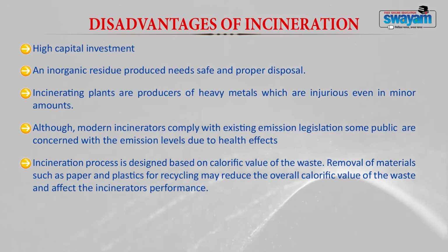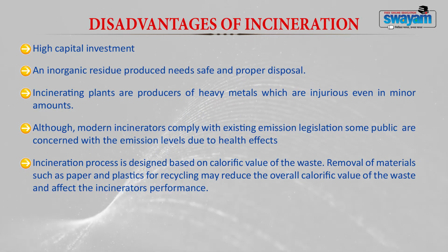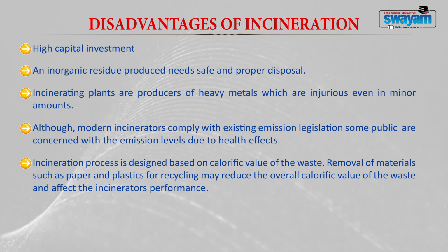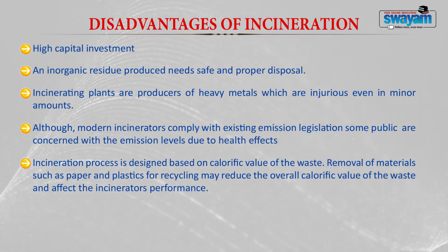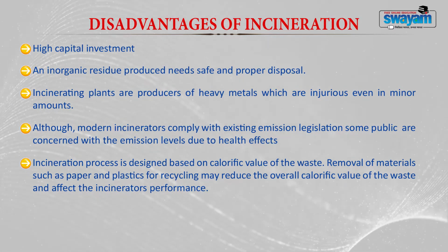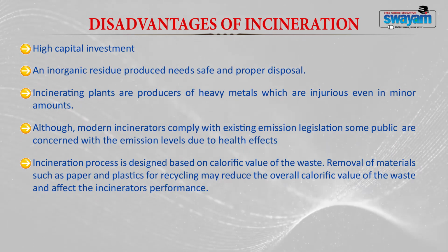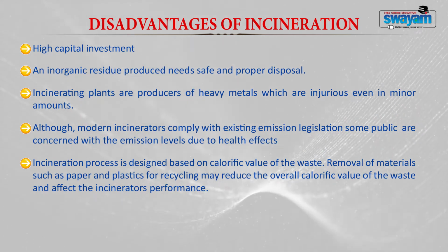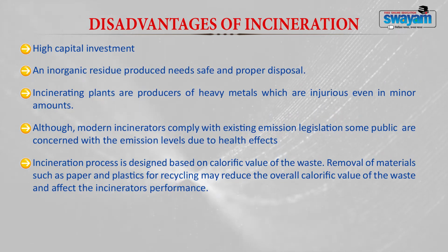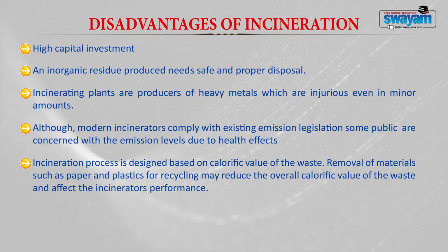Now, the calorific value is what generates heat, and with this heat you convert it into electricity. When you recover materials like paper and plastic, the overall calorific value of the waste gets reduced. Once it is reduced, obviously the heat generation will be less, and the energy recovery from the waste will be minimized. Sometimes that becomes a major disadvantage of the incineration process when you are planning to recover some energy.